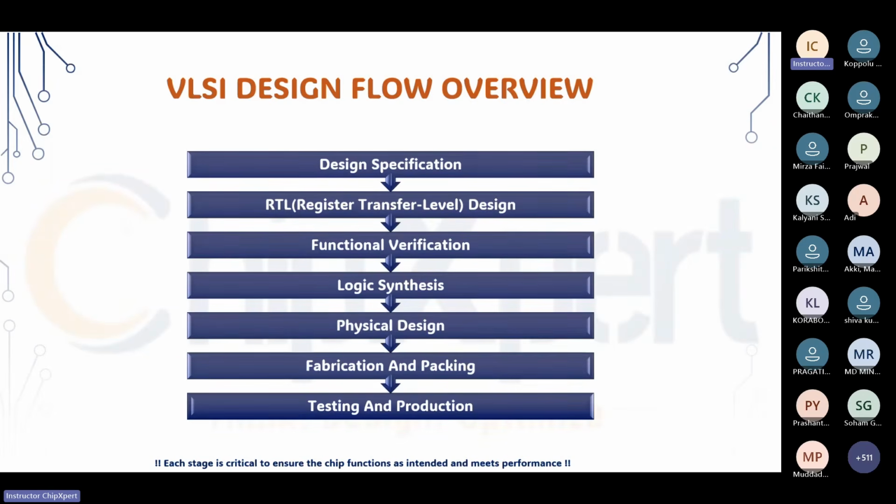How do you optimize? The simple technique we see in digital electronics is the K-map. That is how you synthesize the logic. With that synthesis, you will have an optimized logic in the format of Verilog code. Verilog is a hardware description language. Whatever the circuit is, the AND gates and OR gates, will be represented in the form of text format.